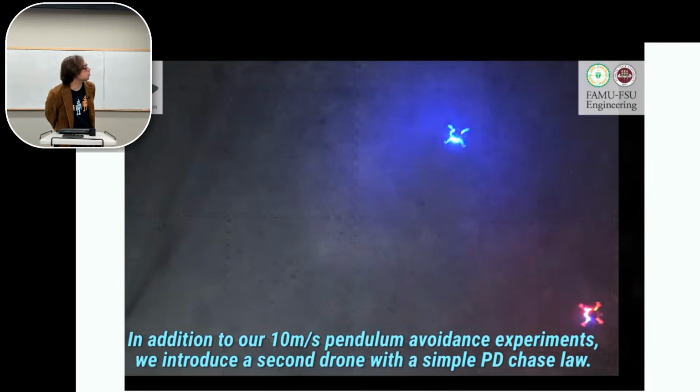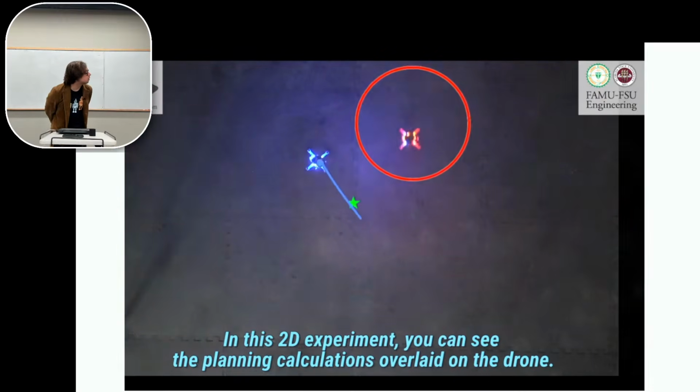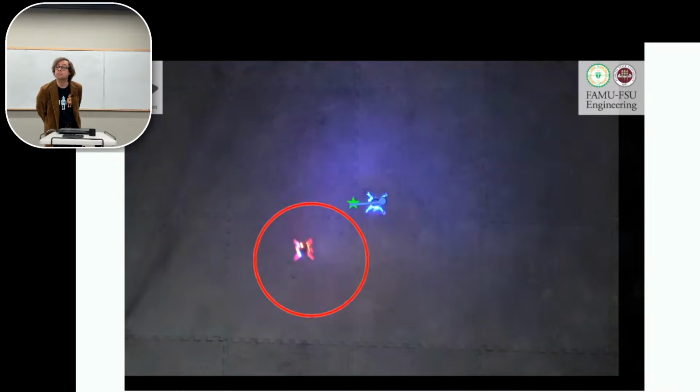And so here we can show it on actual hardware, and these two drones are basically playing tag, more or less. That blue drone's trying to stay in the middle, and this red drone's chasing it down, which is the PD control law. But here, you can see the blue drone's thinking. That's the model prediction. That blue line, that's the path. And that's being computed with a quadratic program.